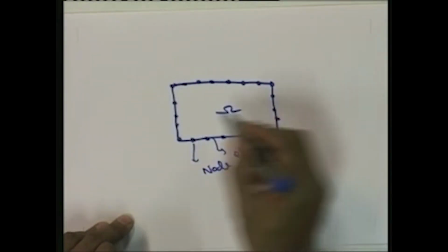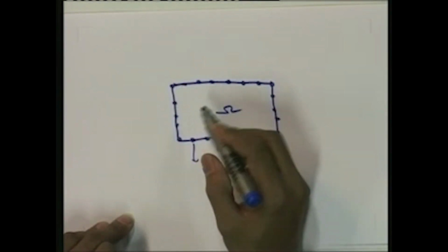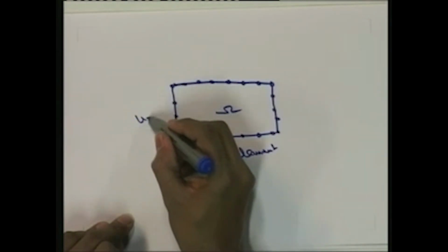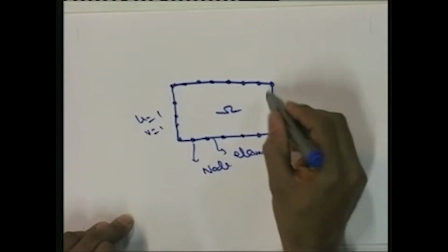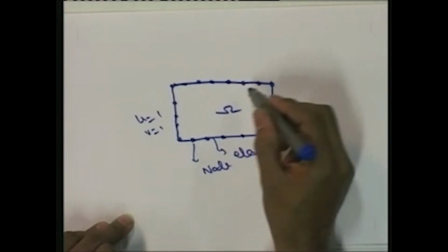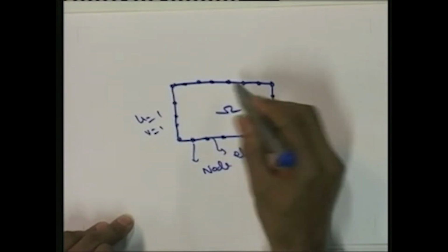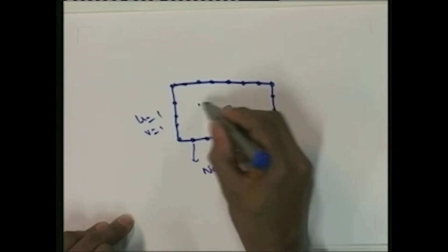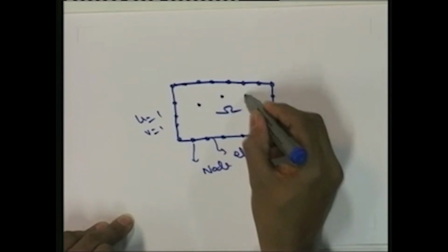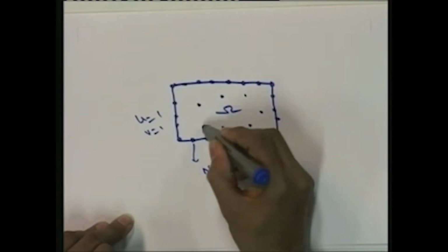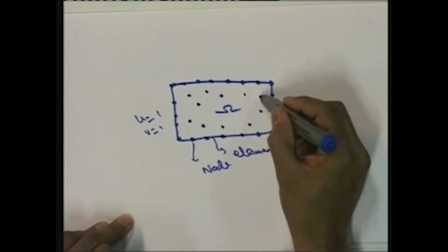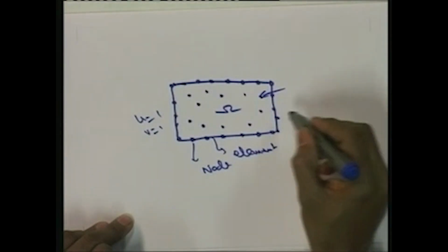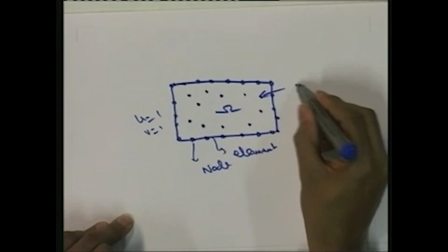For this particular problem, if the velocity here is known and on some other portions the velocities are not known, then we can find out first on the boundary, and various internal points we can define separately after the boundary integral equations are written. Then we can solve for the unknowns inside the domain. These are internal nodes.